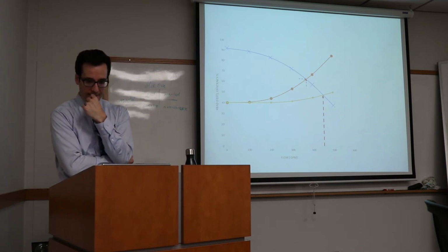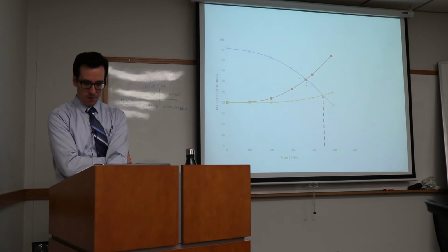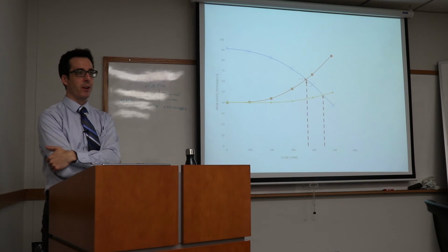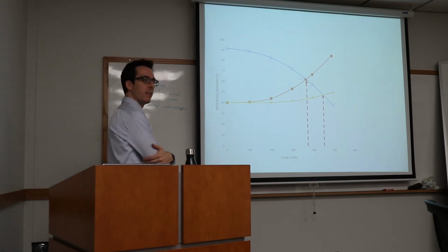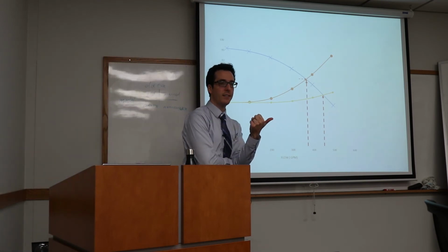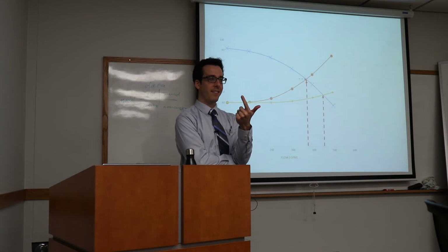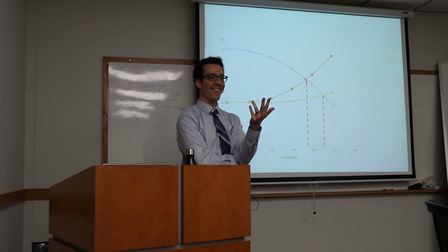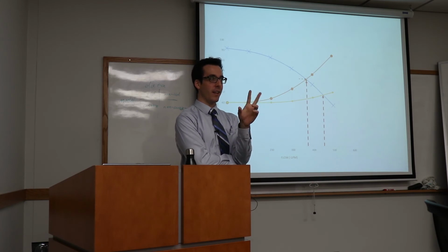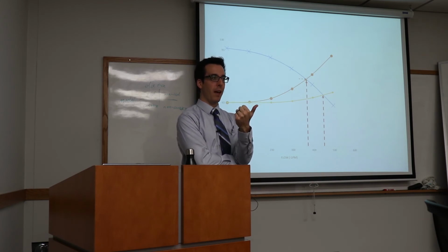Okay, so let's suppose that we want to get it back to our design point of 370. What do we do? Install the VFD. Okay, that's one option, VFD. Valve, the throttle. Okay. Trim the blades. Very good. So excellent. So let's talk about those in reverse order. So trimming the impeller, what does that do?